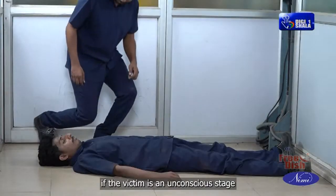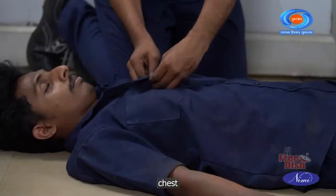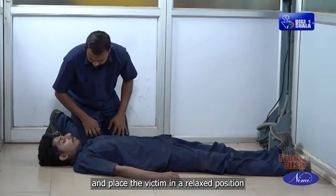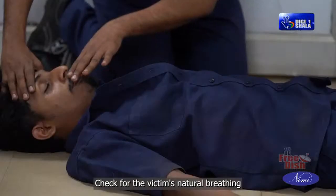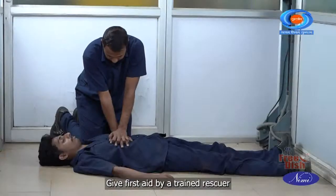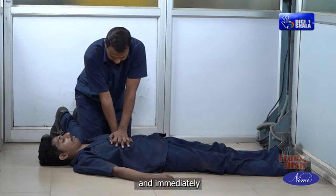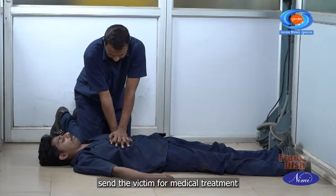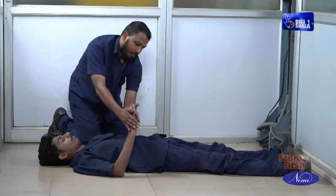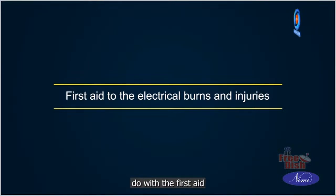If the victim is in an unconscious stage, then loosen the clothing of neck, chest and waist and place the victim in a relaxed position. Check for the victim's natural breathing and consciousness. Give first aid by a trained rescuer based on the condition and immediately send the victim for medical treatment. Keep the patient warm.